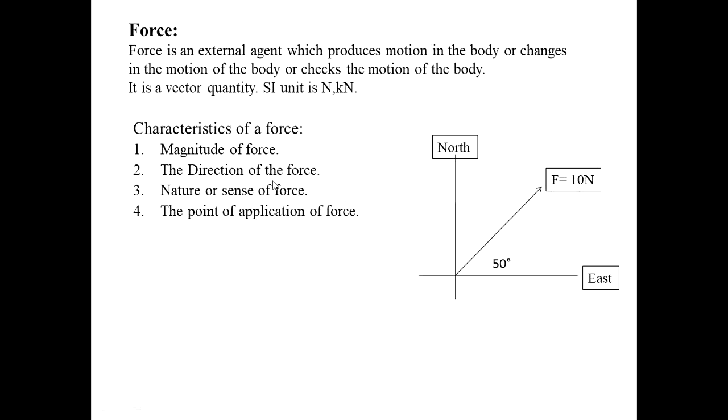Then next, direction of force. Direction of the force means in which quadrant the force lies: first, second, third or fourth. Basically this force lies in the first quadrant, and inclination with respect to x or y. This is 50 degrees with respect to x. So direction is northeast, first quadrant, 50 degrees with respect to x.